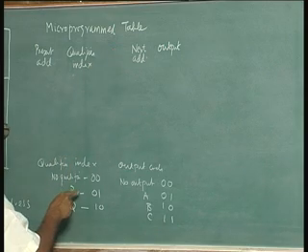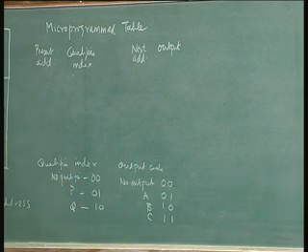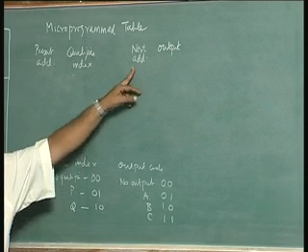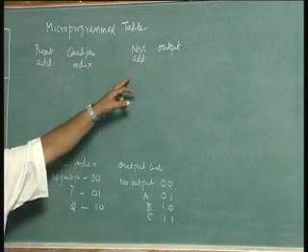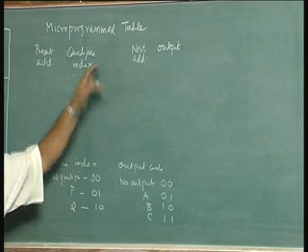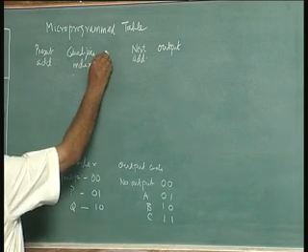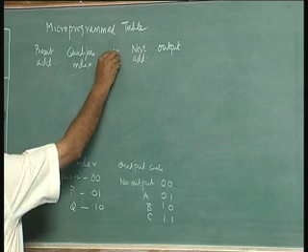When a qualifier test is done, the next state is given here, and I like to know whether that state is reached if the qualifier is true, or if the qualifier is false. I need to know whether the next address given by this table is a true address or a false address. So, I will have to put a true or false bit.